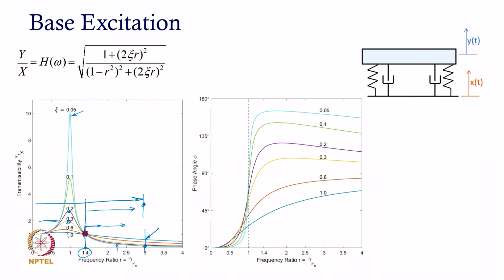But if I have a large level of damping, even 0.6 or 0.3, they are going to generate a much higher vibratory response. Now, it does not show up in the linear plot because the dampings are so close, and there is a huge difference between 1 and 0.1, right. So, 10 times drop, but they will not show up. So, we will have another slide in which I show this in a dB plot or a logarithmic plot. There you will find a huge difference in the way the damping plays its role.